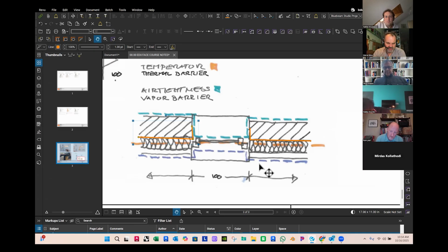One is used on the outside, which is capable of having more a direct rain protection sort of thing, but still lets vapor from inside to the outside, while another tape on the inside, window profile around the corner, for instance, allows humidity to pass by from high pressure, let's say, showering vapor. It's hot. That is allowed to evacuate through the system then.